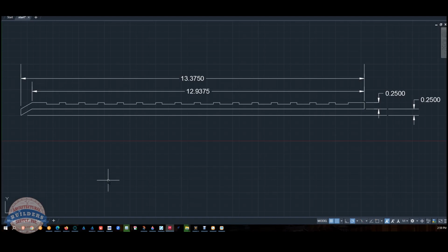There's less to remove. Now imagine what's going to have to happen to make this 13 3/8 wide piece of 1/2 inch thick aluminum. We're going to have to first run a V-bit to create this profile, and then all these pocketing profiles. I think it's about 4 foot long. It's a lot of pocketing. Then we're going to have to flip it over, and we're literally going to have to run a V-groove here, so it'll actually look like this, and then pocket all of this. So if this is 1/4 inch, and this is 1/4 inch, wow, that's a lot of aluminum.